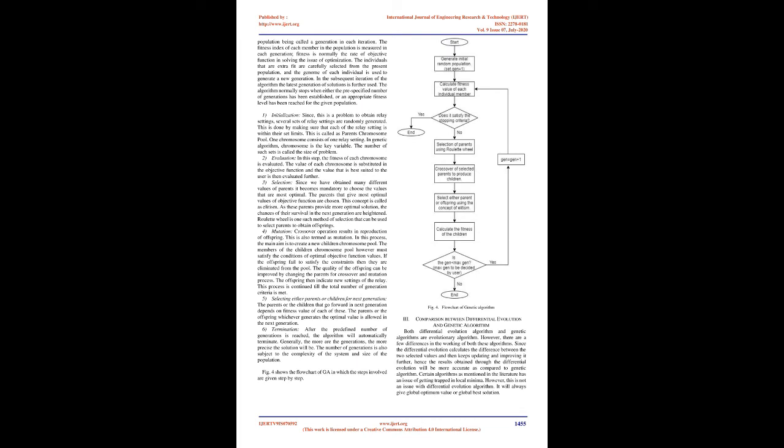1. Entering the inputs. The first step in the algorithm is giving adequate inputs. The data that is given as inputs include the size of the population and the maximum number of generations for which the optimization is to be carried out. The data regarding the fault current values, CTR, maximum and minimum limits of TMS and PSM. The population size does not vary in the entire course of the optimization process of the algorithm. 2. Initialization. The initial population is chosen such that it covers the entire search space. Here, since the optimization of PSM and TMS is considered, those parameters will be initialized considering their respective limits.